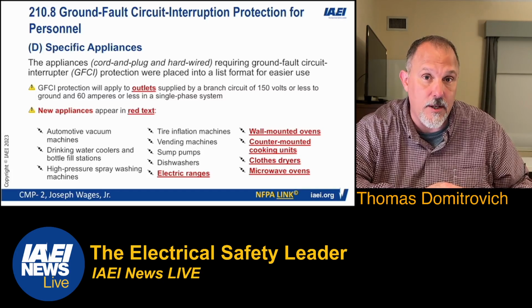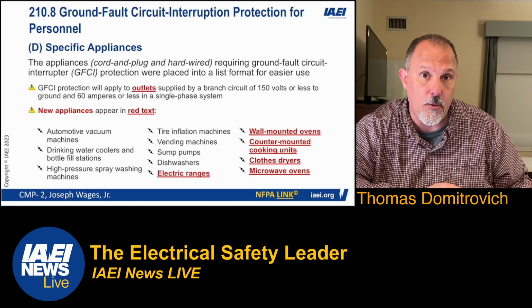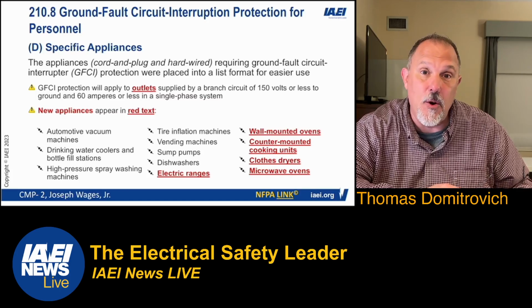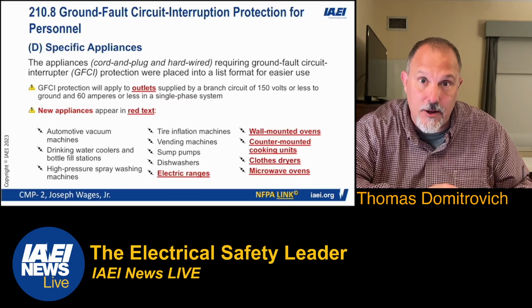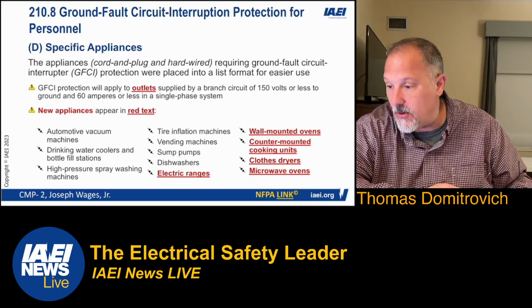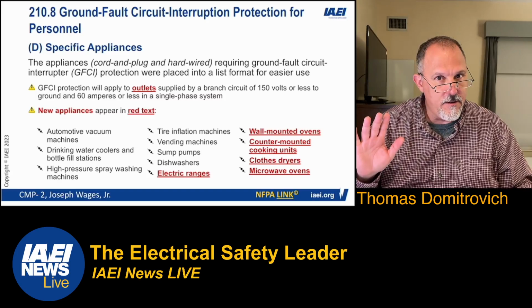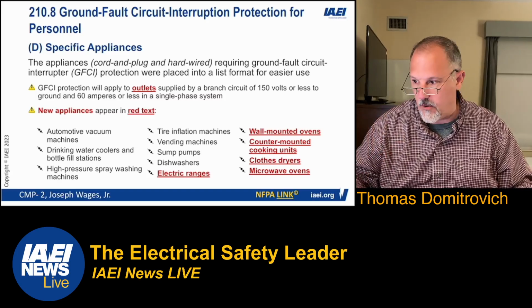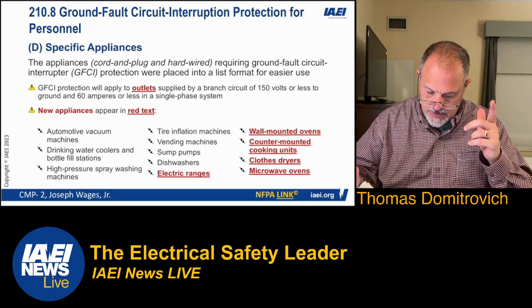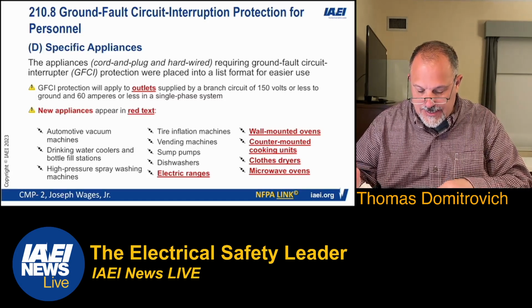These are deaths that we're talking about. People who are working on this equipment. I don't really care if they were qualified or not. They did not deserve to die. So we've expanded the GFCI protection. This is for outlets, whether it be cord and plug connected or hardwire. Doesn't really matter. And that's 210.8D.